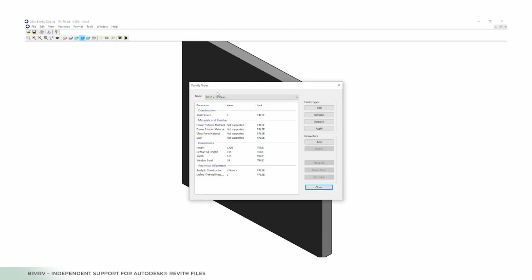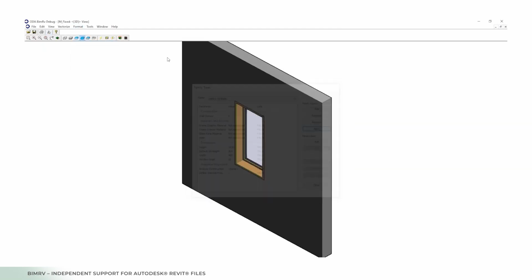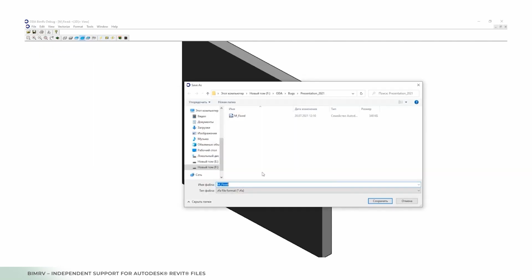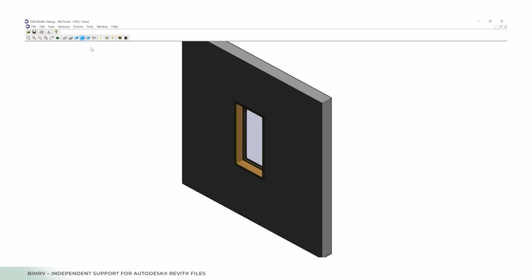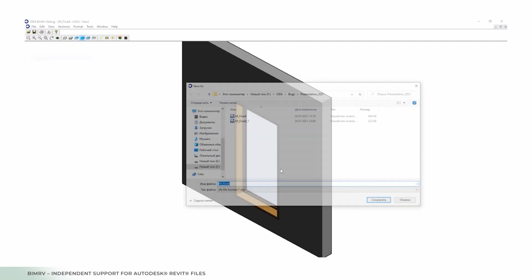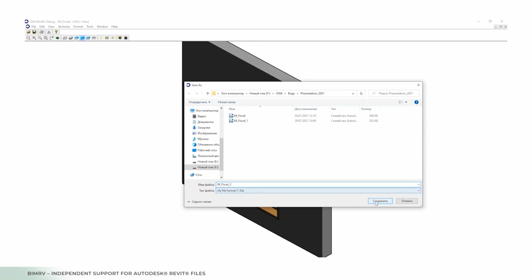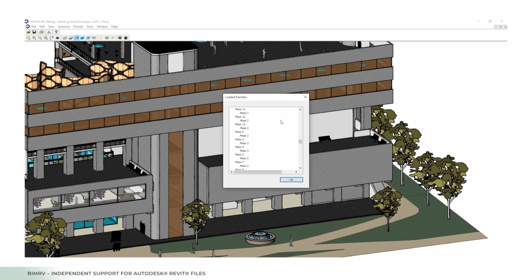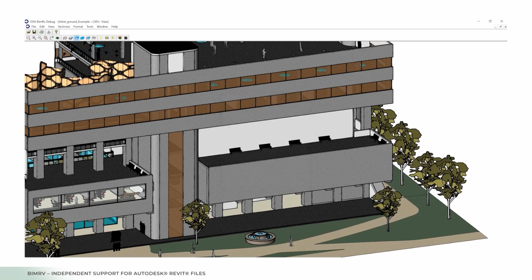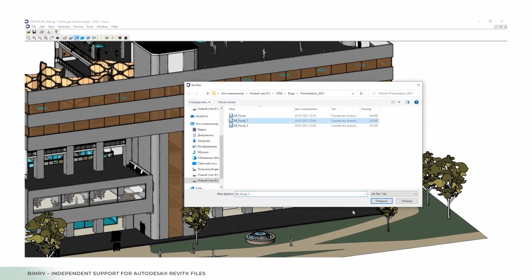We continued working on recalculating family geometry by family types. A family contains geometry only for the active family type. We implemented the initial version of rebuilding geometry by type. Recalculation of the family geometry requires a constraint solver. The solver is used to update and verify sketches of forms, modification dimensions, and reference planes. If the verification passed, then the geometry of the form can be recreated. So we need to update the geometry of all forms in the family and perform Boolean operations on them.